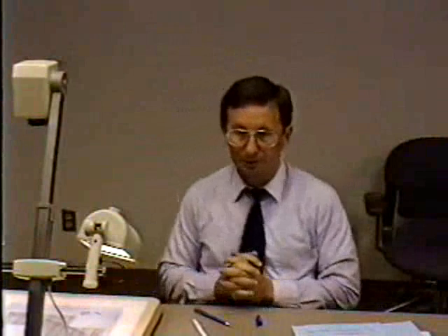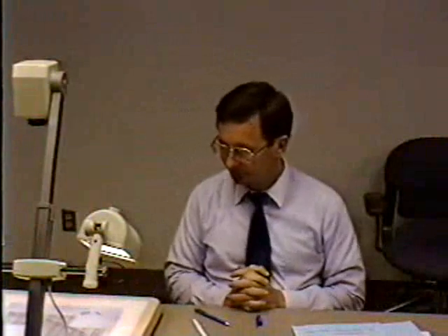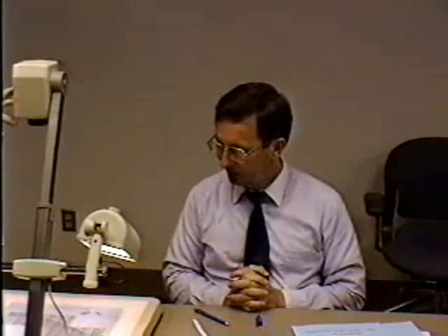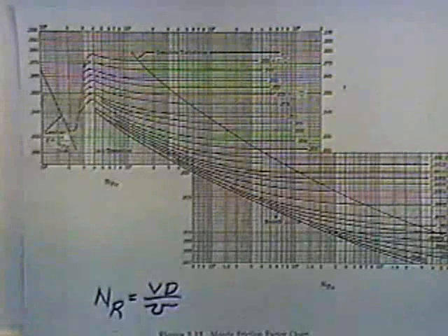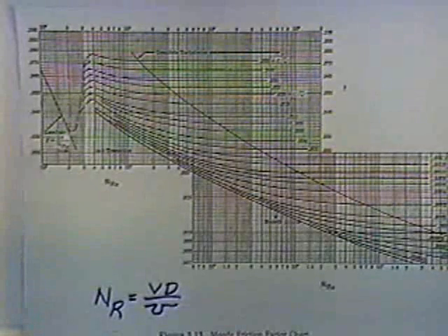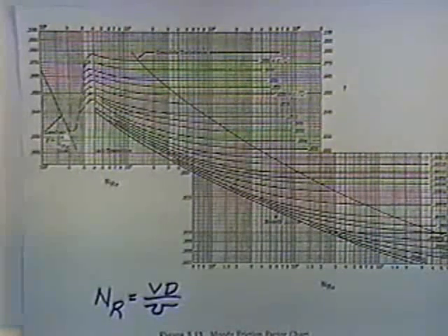This is the old Moody diagram. There were a lot of experiments made historically on establishing roughness coefficients for different type pipes and so forth. And finally Moody came along and took all the data and put it into this one diagram. And so we've been using this thing for decades now. It's in a lot of different references, a commonly accepted, widely used set of information. And so you estimate your f, your friction factor for the Darcy-Weisbach equation from this.